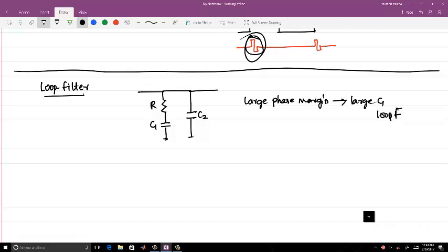No problem. When you are designing a PLL up to close to, let's say, 5 gigahertz or 8 gigahertz, a ring PLL, do not get scared when you see a capacitor number of 100 picofarad right now. There will be ways we can realize a larger capacitance by using smaller capacitors. We will look into that later once we get done with the oscillator.